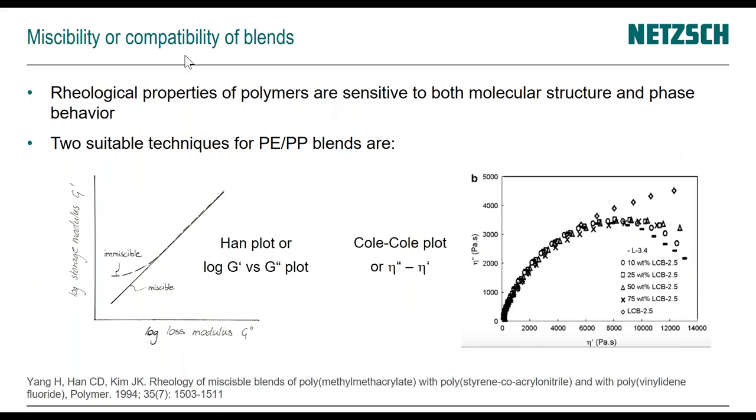And if we want to study miscibility or compatibility of blends, that is also possible with rheology, because it's very sensitive to the molecular structure and the phase behavior. When I talk about miscibility and compatibility, it tells us if we have distinct phases or if we have really good adhesion between the materials, so it behaves like a homogeneous new material, and that will have a huge effect on the mechanical performance.